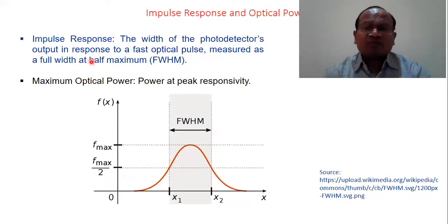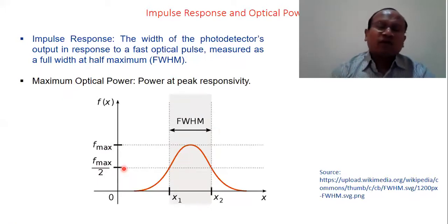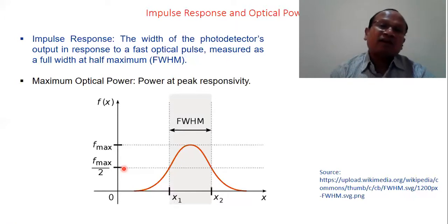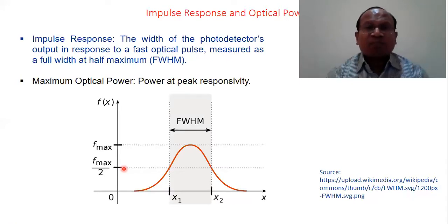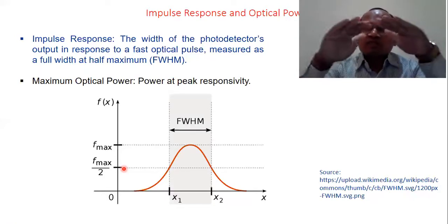If you see it in terms of power, it is the same concept; half power we are taking. When we calculate in terms of voltage or current or instantaneous value, it's RMS, but when you calculate in terms of power, it's half. Actually, the concept of bandwidth is 3 dB bandwidth, and 3 dB bandwidth means the signal is lower by 3 dB from its maximum.